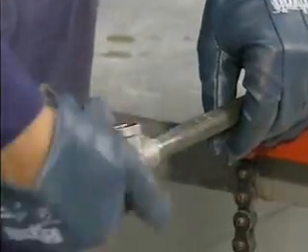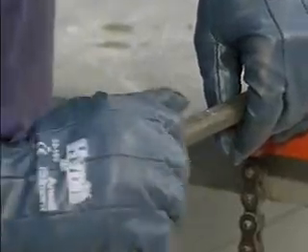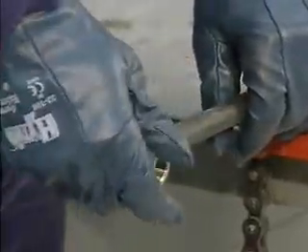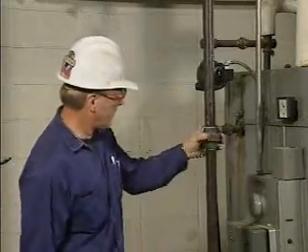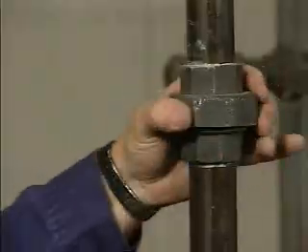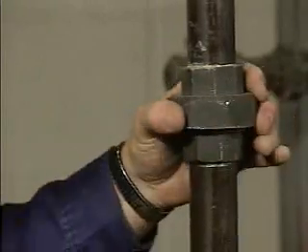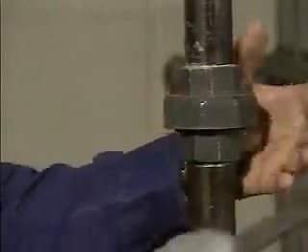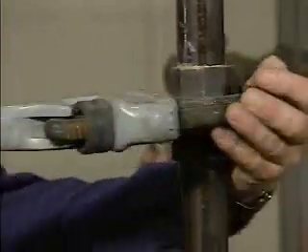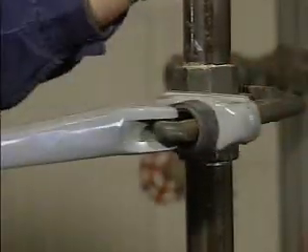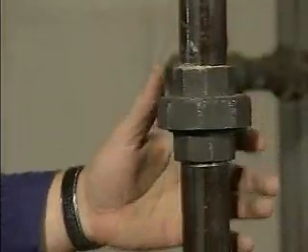Threaded joints are typically used for smaller pipe sizes, which carry lower pressures. Threaded joints are relatively easy to make and they don't require welding. This is an advantage in places where fire hazards exist. On the other hand, threaded joints tend to weaken the pipe wall because the pipe's wall thickness is reduced at the troughs of the threads. Threaded joints are also subject to leaks if they are improperly tightened or sealed.